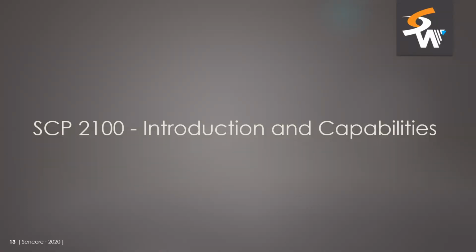And the second thing that comes along with that is there are no null packets in there now. Their downstream receiving equipment, most of it, is set up to receive a constant bitrate transport stream with some percentage of nulls in it. It has a buffer defined on the front end so it can ingest the stream, account for any latency or jitter in the physical layer, put that into the buffer, and clock it out into a nice, smooth transport stream inside the device in order to do its processing.